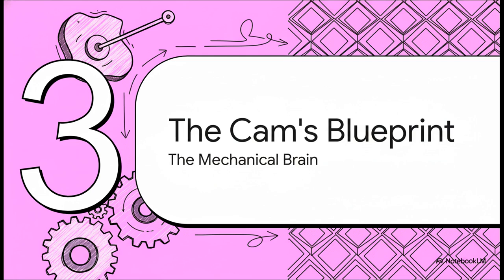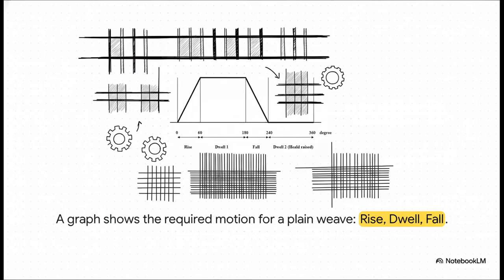So if the shed shape is that important, what's controlling it? Well, this brings us to the mechanical brain of the whole operation, a surprisingly simple device called a cam. Now, before we see the cam itself, we've got to understand the instructions it's following. For a basic plain weave, the threads need to do four things: rise up, then dwell, which is just a fancy word for hold still, then fall back down and dwell again. This graph is like the abstract blueprint for that entire motion.